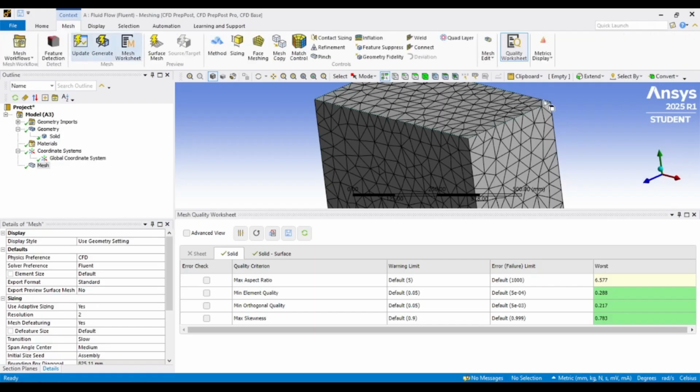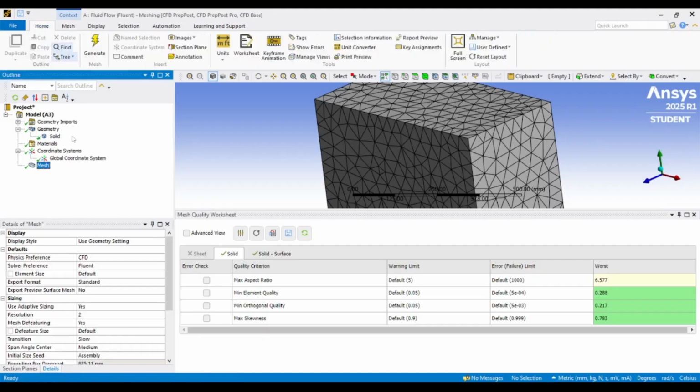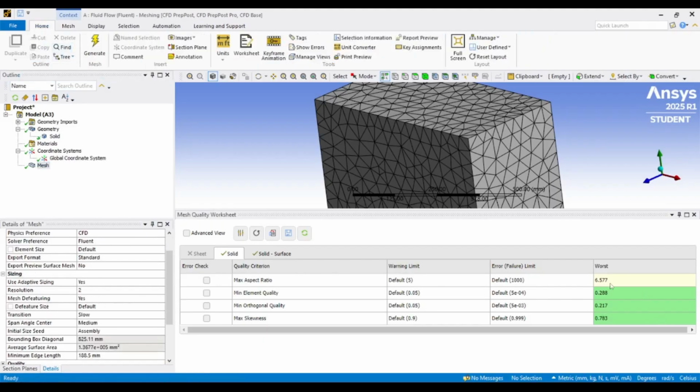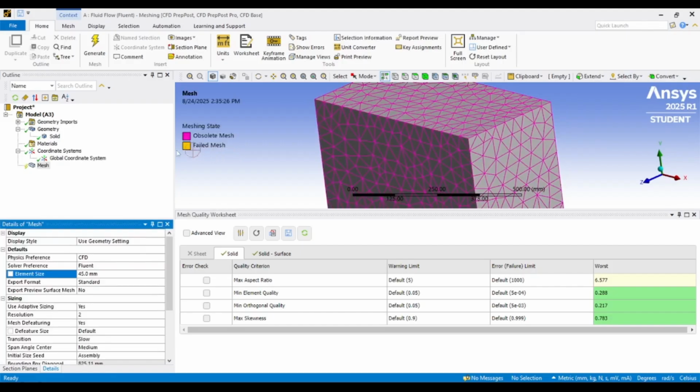For a deeper quantitative understanding, monitor lift and drag coefficients on the cylinder during the transient simulation. You can do this by creating surface monitors for force reports and plotting them versus time. The drag coefficient will fluctuate slightly around a mean value, while the lift coefficient will oscillate with a frequency related to the vortex shedding process.